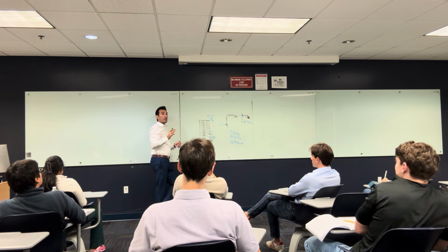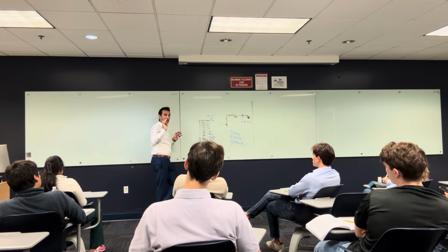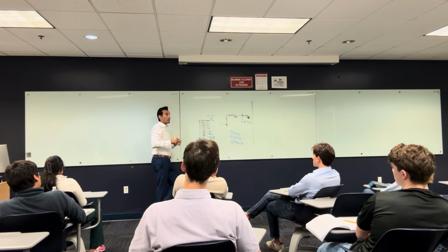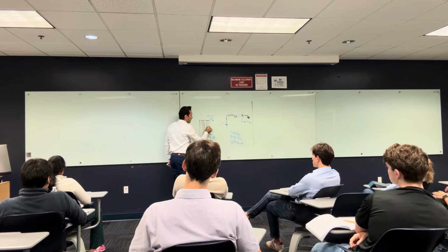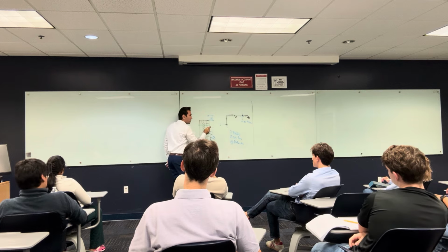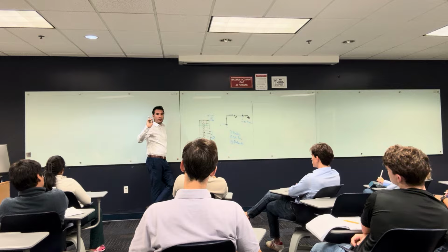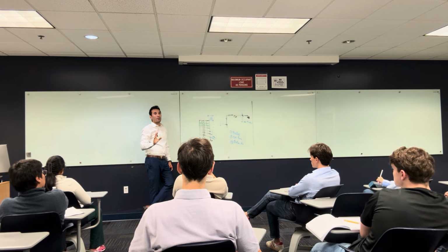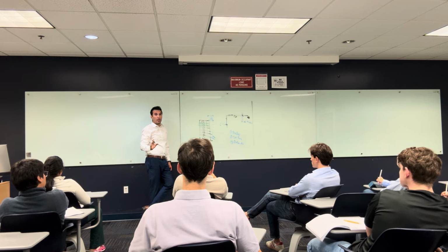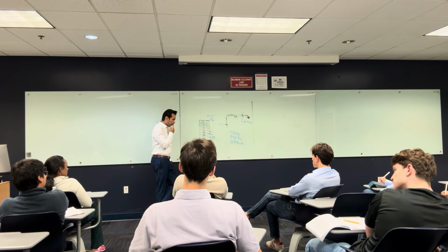No, I'm saying in the elements. We have columns, we have beams, we have slab. What are the elements that are the heaviest? Slabs. That is 90% of the weight of the structure. Here is where you have all the dead load, all the live load, all the rain, the roof live load, and the snow load. They are all here at the slab system. Columns, shear walls, all this is around 10% of the weight of the structure. So most of the mass is coming from the slab system.